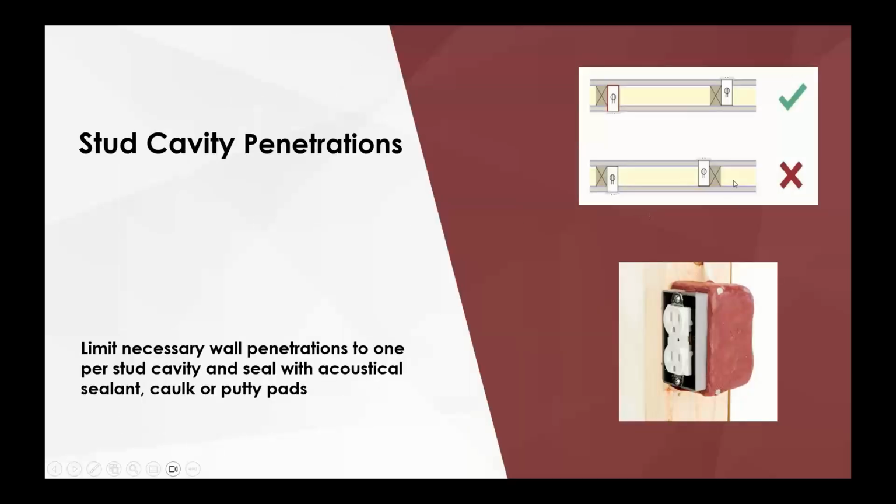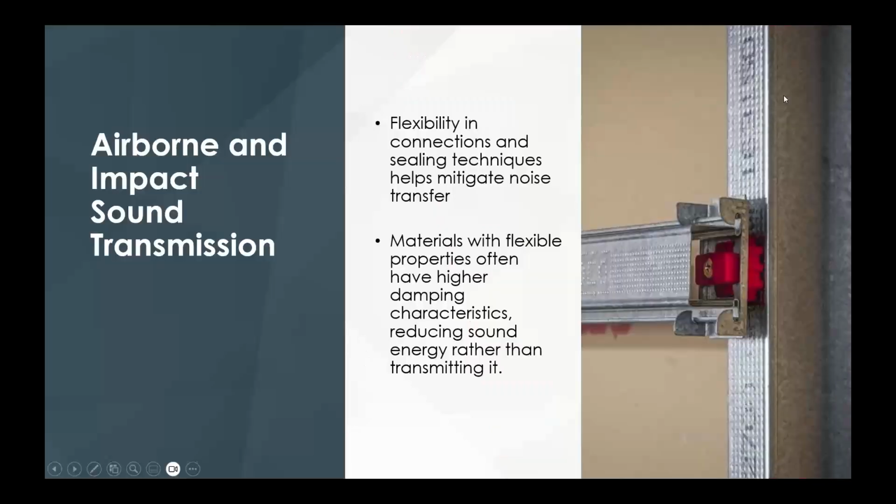So again, just to dive down a little bit deeper, we don't want to see outlets in one stud bay, two of them. We want to go in opposite ones. All right, so let's talk a little bit more about that flexibility, airborne and impact sound transmission.